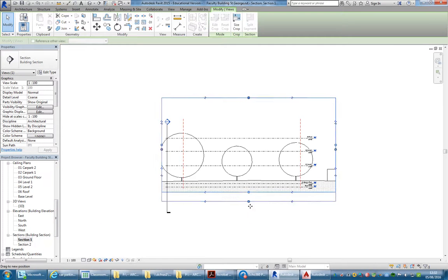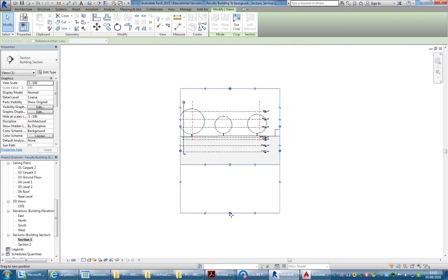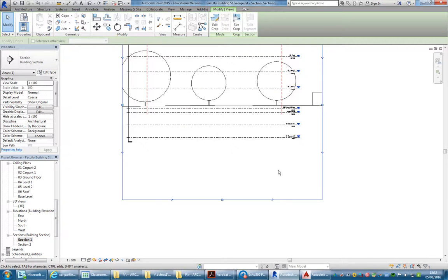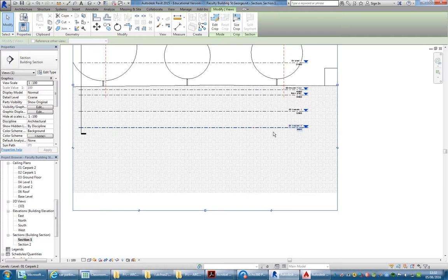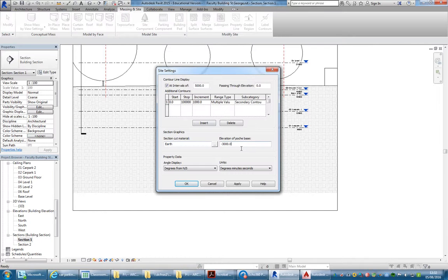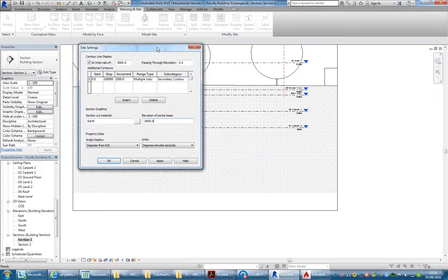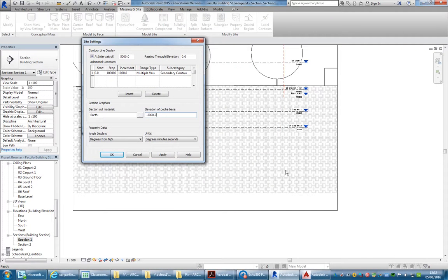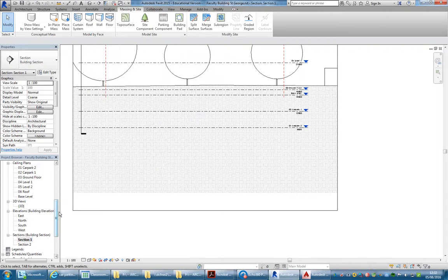Right, so I'm going to bring this down a bit, and you'll see down below the base, we've got the hatch pattern stopping there. So you've got to check that level first. And so just, again, showing that option. So it's minus 3,000. So 0 is down here, and that means the hatch pattern finishes 3 metres below that. So that's okay, but we still can't see the hatch pattern in the plan.